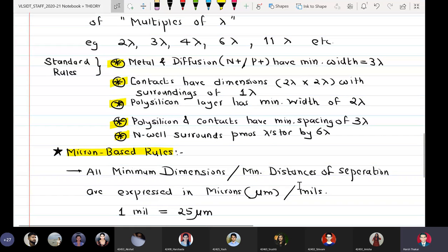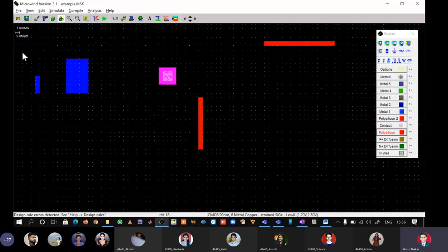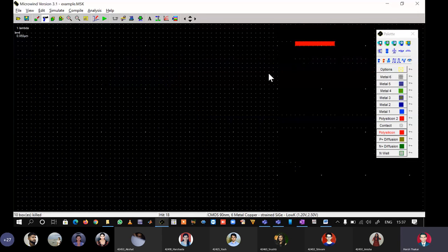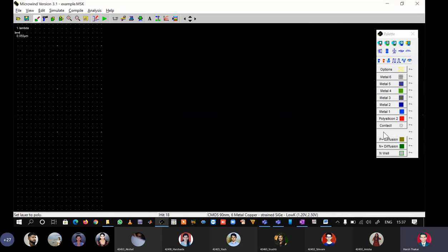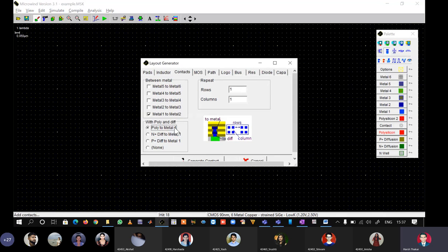Polysilicon and contact should have a minimum spacing of 3 lambda. So let us bring a polysilicon and a contact. Delete everything. Let us bring a polysilicon here. Let us bring a contact also here.